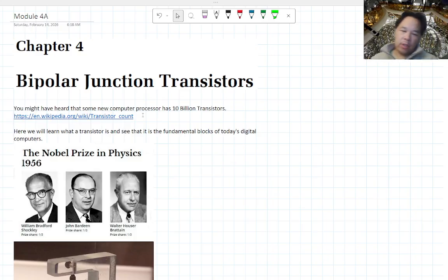This is where we're going to see the concept of the transistor, even though the bipolar junction transistor that we're going to describe physically is not exactly what they're building computers out of. They actually make it out of MOSFETs, so it's a field effect transistor instead. But that's just a manufacturing convenience. It's not that they functionally are different. It's just not as easy of a shape to make a lot of bipolar junction transistors versus the field effect.